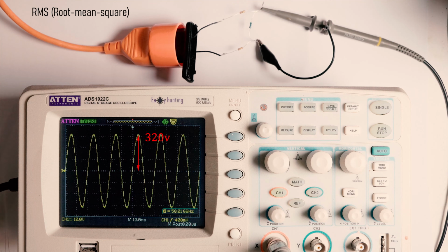This also explains the little secret of the increased voltage after the bridge rectifier and capacitor. Of course, the capacitor is charged to the amplitude value of the sinusoid, which gives the illusion of an increase in voltage. All measuring instruments, including multimeters, are of course aware of this secret, and when measuring alternating current, reduce the resulting value by a fixed factor, which, by the way, is equal to the root of 2.